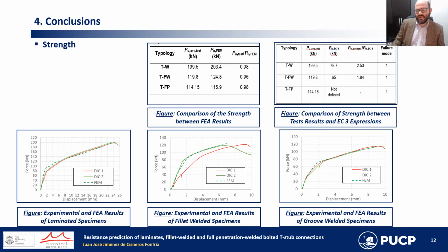The following conclusions can be drawn from the works presented above. The strength of the continuous T-stub is the highest. This fact is produced because the value of the M factor is the lowest, and because of the influence of the fillet radius between the web and the flange, which avoids stress concentration in the material. On the other hand, the difference appreciated between welded T-stubs is very small.